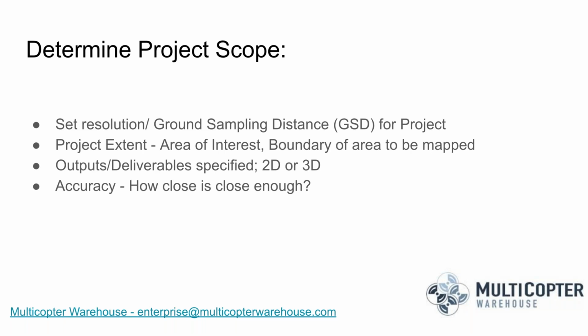Without any kind of geo-reference information, you can get fairly accurate data out of most UAVs, but it depends on really how you're measuring that accuracy, whether it be relative or global. Okay. Why would you not always want the best accuracy or the smallest GSD?